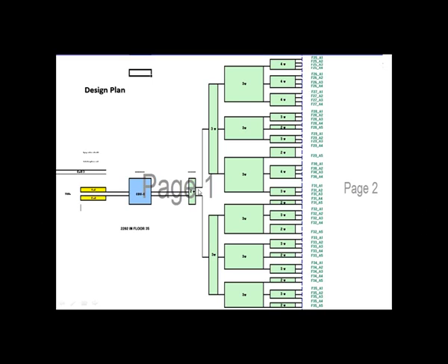This is a two-way splitter, then we feed three-way, because the overall number of antennas we had was from 25 to 35 floors, which is about 10 floors. Each floor had 4 antennas. Okay, so 4 multiplied by 10 is like 40 antennas. So we had to split our signal. It's just an example. I'll go through a simpler system as well. So we had to do the splitting. So if I start to do a simple calculation over here for your understanding,